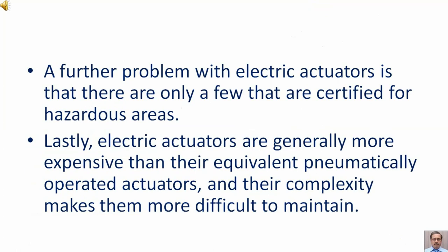A further problem with electric actuators is that there are only a few that are certified for hazardous areas. Lastly, electric actuators are generally more expensive than their equivalent pneumatically operated actuators, and their complexity makes them more difficult to maintain.